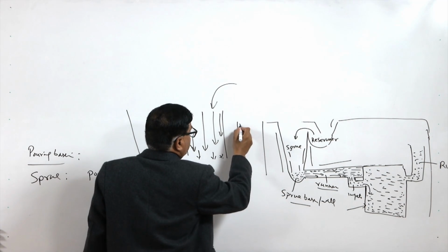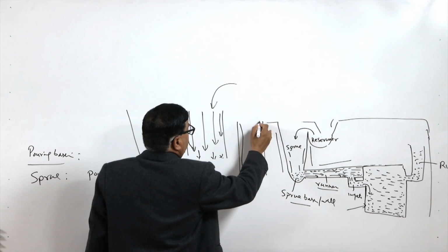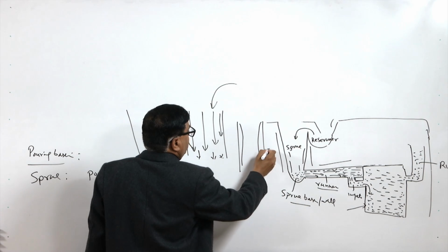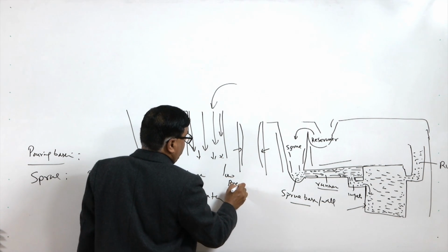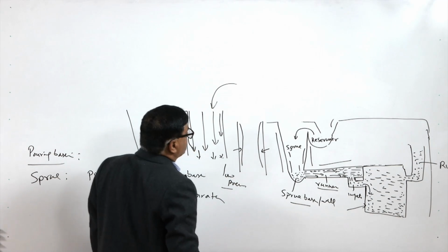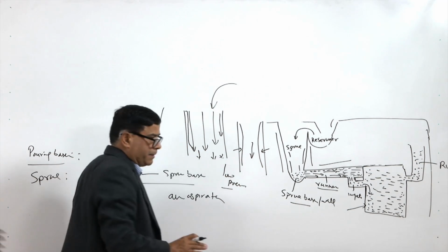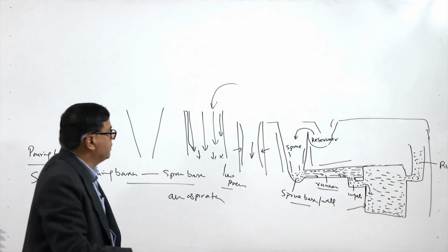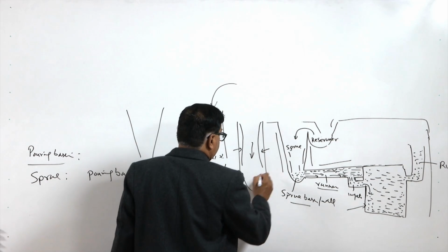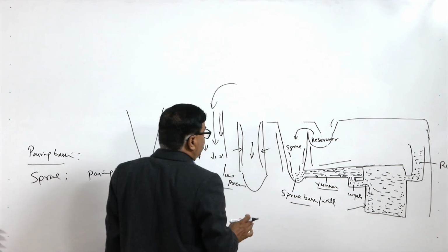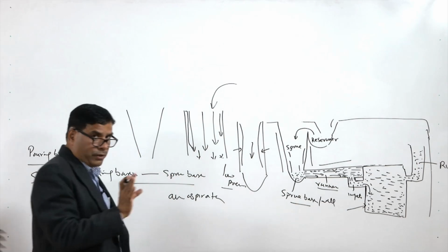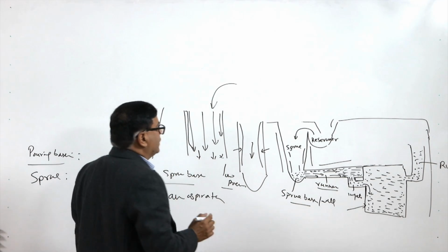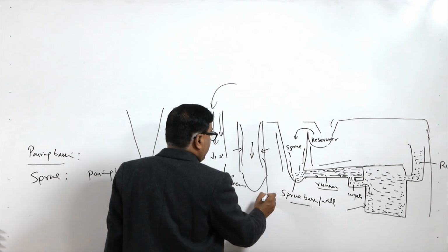This separation in the lower zones leads to the development of low pressure regions due to the increasing velocity of the molten metal during its journey from the top to the bottom of the sprue base, and that leads to air aspiration from the porous molding sand.